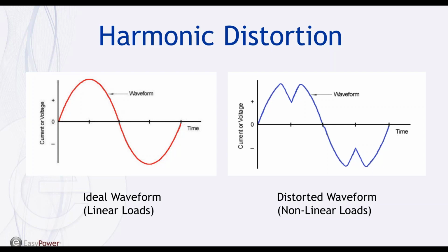And here you can see what I mean by an ideal waveform having 0 harmonic components. The waveform on the left does not have any harmonic components and is essentially a pure waveform with linear loads. Linear loads draw current that is sinusoidal in nature, so they generally do not distort the waveform. Nonlinear loads, however, can draw current that is not perfectly sinusoidal, as shown in the figure on the right. Since the current waveform deviates from a sinusoidal wave, voltage waveform distortions are created. As you can see, waveform distortions can drastically alter the shape of the sinusoidal waveform.